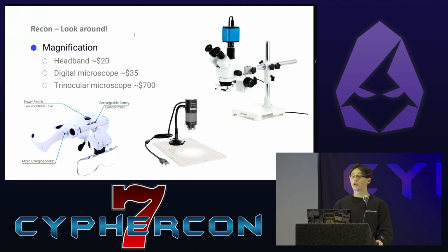In the middle is a digital microscope. These are really cool as well. You can hook them up to your computer, a phone, a tablet, and get a live feed. But I think the biggest problem with these is that you lose your depth perception. So if you're trying to solder staring at the screen, it can be really hard to tell how high your iron is off the board. That said, they are really great for taking photos as you work for documentation or reporting purposes.